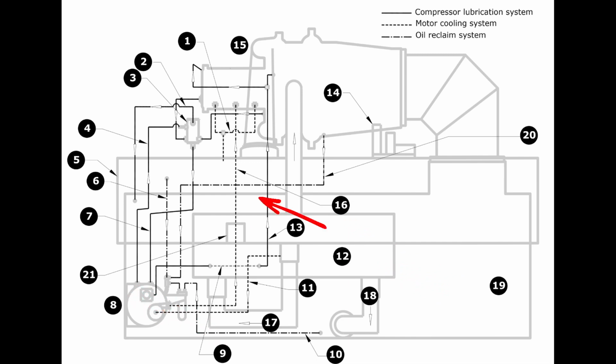So instead of being a screw compressor, it's a centrifugal, and we don't want that oil to make it back to the compressor at all. That is not a good thing for this compressor. Those small droplets of oil turn into basically buckshot and blast our aluminum impellers, and they don't appreciate it. So we have an oil tank or an oil reservoir that is separate from the compressor. We don't have an oil separator or anything like that, so it's a very different design from the screw system.